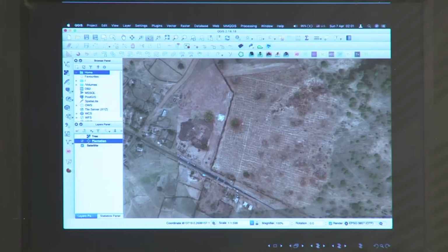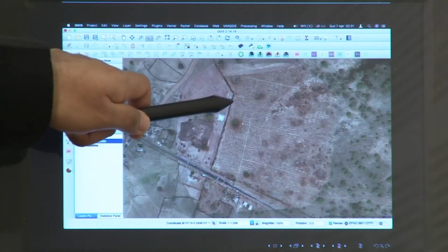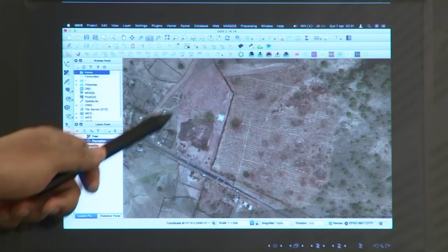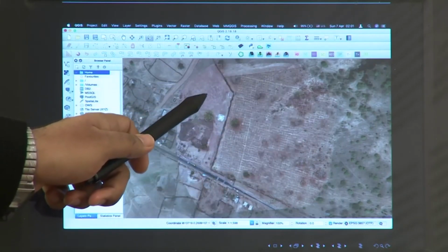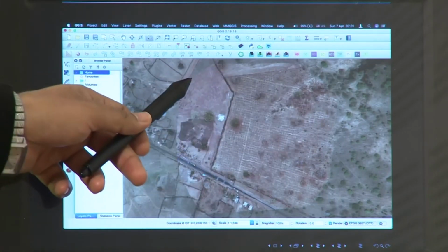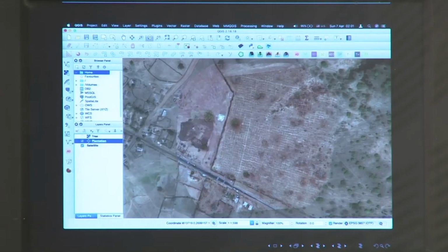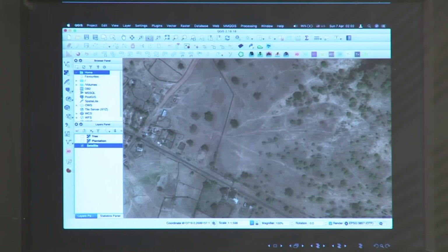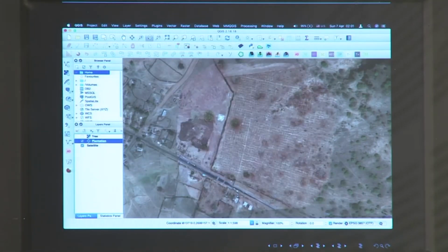In this case what we did was we took several individual photographs. The drone flew over the whole area, and at certain distances it was taking the pictures. Now, all of these pictures were then processed so that they become a single image, and this image was also georeferenced. So, if you look at the previous image and at the location of this road, and now have a look at the drone image, you will see that the road is falling on the same point.